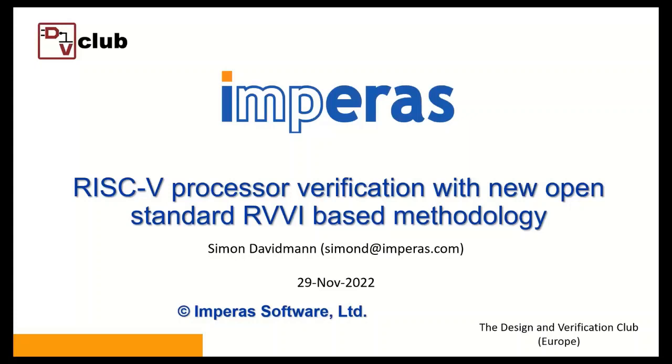But what I showed for our solution in Imperas DV, with RVVI it does hook onto Verilator because there's a C++ interface and a DPI interface, so that you can use RVVI and other downstream components with Verilator. But there is a project in CHIPS Alliance to evolve Verilator to have SystemVerilog.